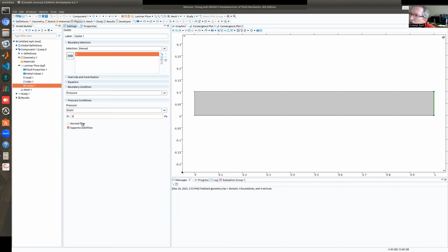The continuity equation, conservation of mass, and two components of linear momentum equation. And in continuity equation, there is no pressure, only velocity. And for the momentum equations, we have pressure derivatives only, dp dx and dp dy. So that's what matters only in terms of pressure.